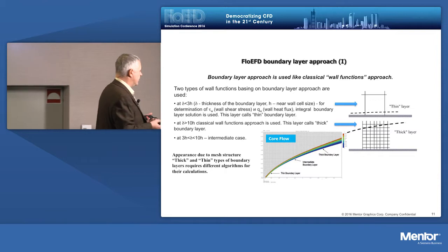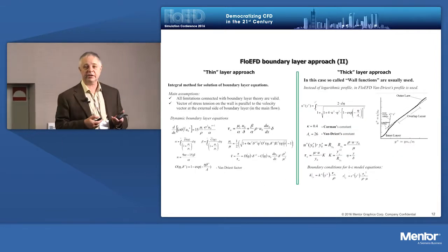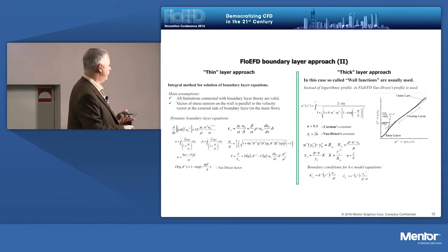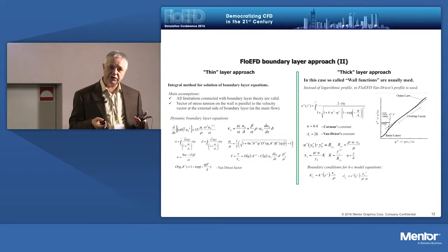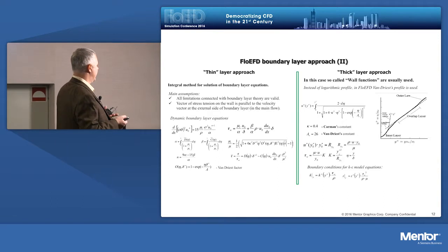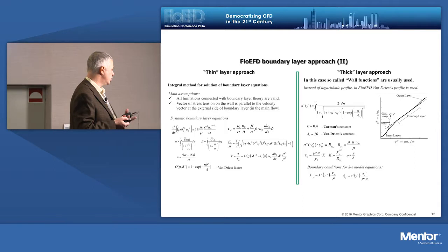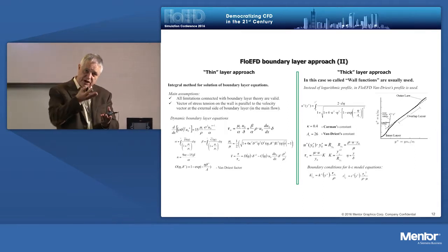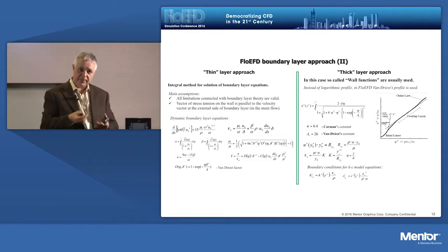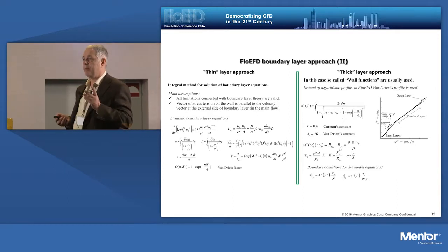Thin boundary layer is mainly based on Prandtl theory. We made some assumption regarding the boundary layer, and the main assumption is that the direction of the vector of stress tension at the wall is parallel to the external velocity. In principle, this does not happen everywhere.